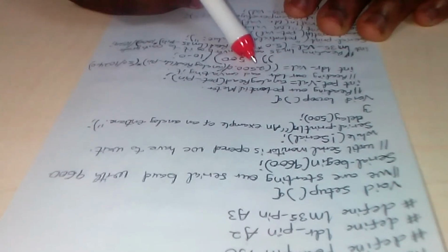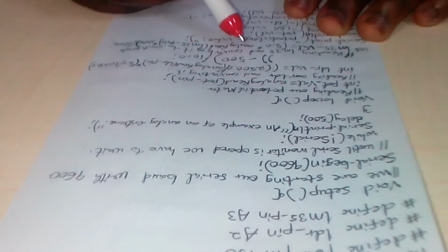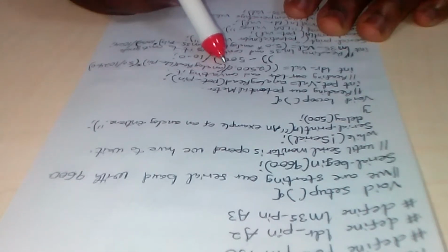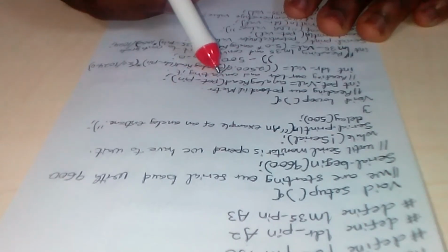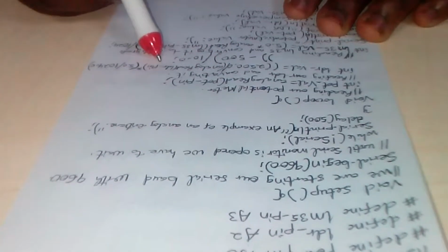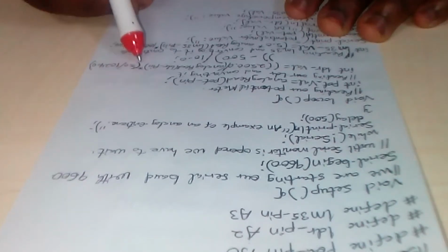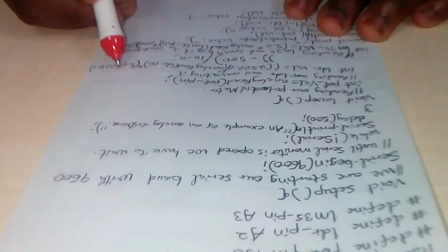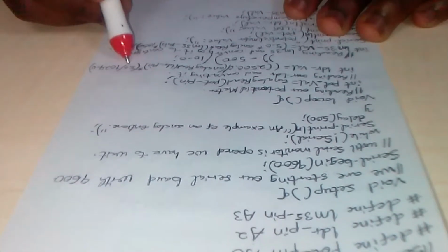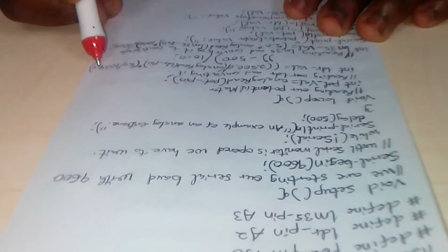Now we have 2500. We have to convert it. It has its own formula. We have 2500, okay, 0.0, okay. Why are we using this point? It's actually like a decimal, okay, divided by, we have our analog read LDR pin, okay. The value it reads. Now times 5.0, because our computer reads digital, we have to actually convert it. 5 times, now we open our parenthesis, okay, 5.0 divided by 1024.0.